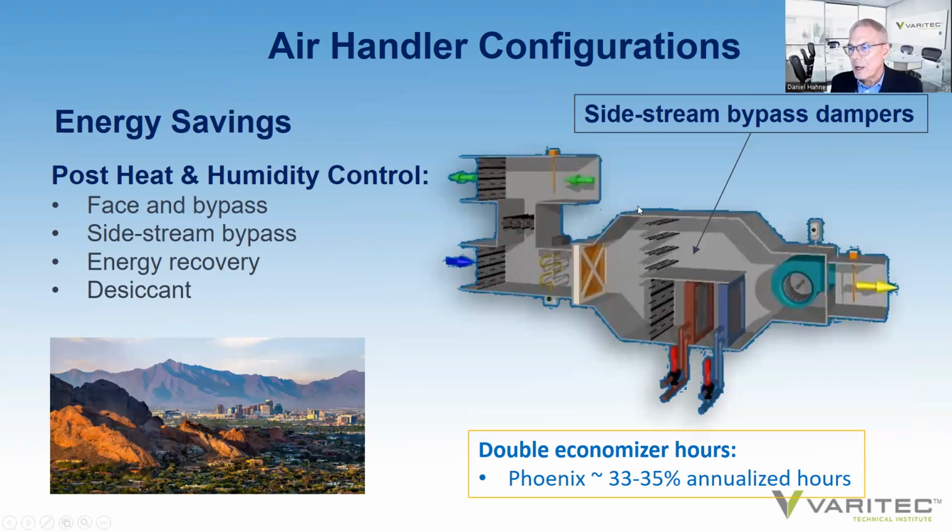With a custom air handler, you actually provide a secondary tunnel adjacent to the cooling coil, and you have a modulating damper that regulates the amount of mixed air that bypasses the cooling coil and is reintroduced into the supply air stream to create a free reheat mode from 55 to 65 degrees. A discharge air temperature sensor is placed at the air handler that modulates the mixed air damper, and that damper modulates open and close to maintain the supply air at 55 degrees.